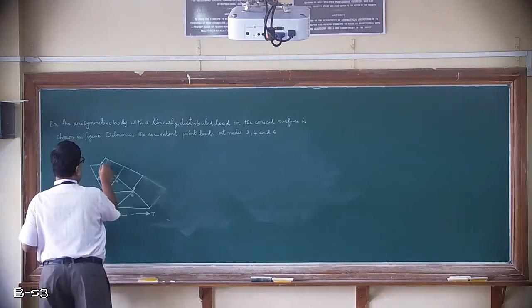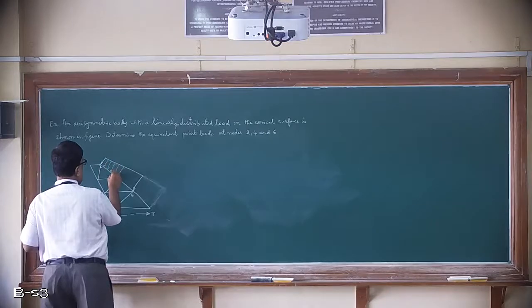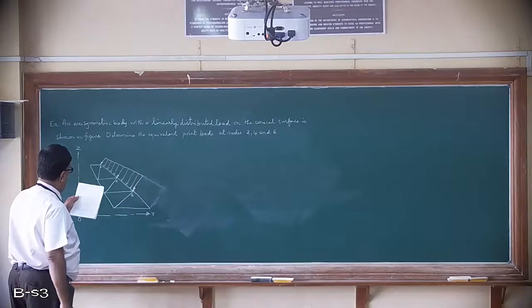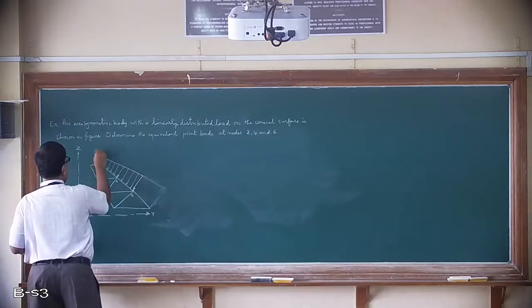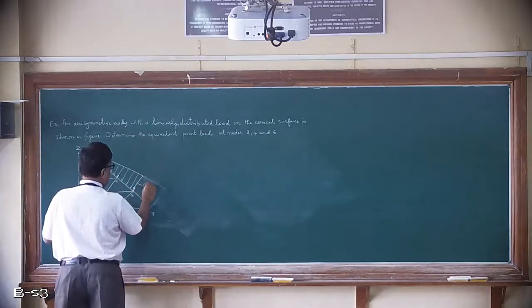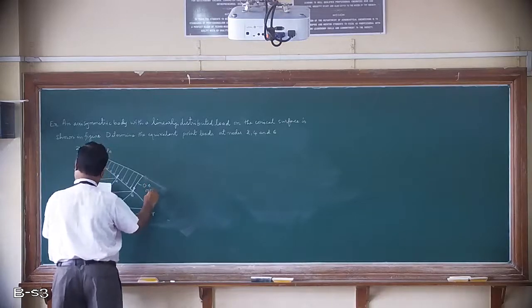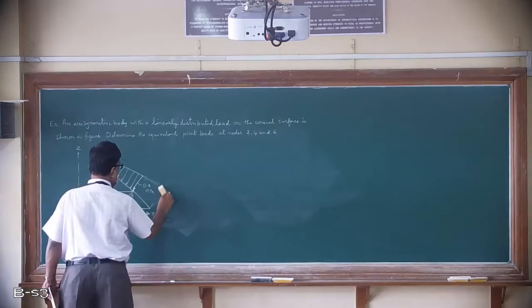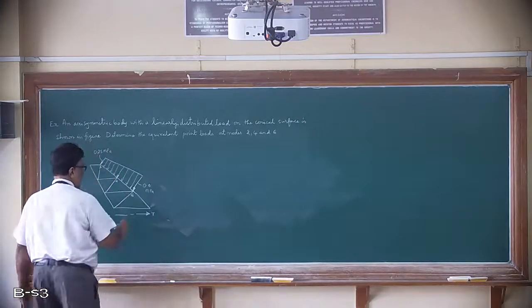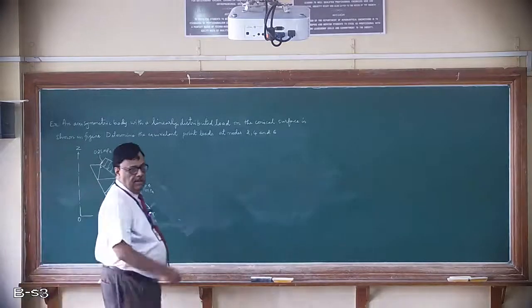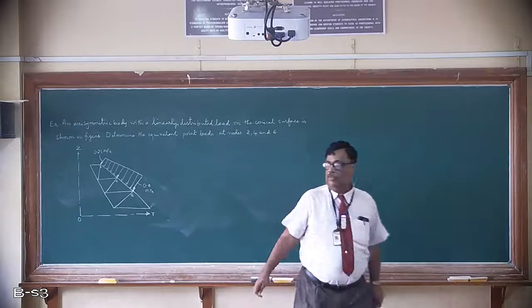Here, all these loads are acting now. These are, of course, acting in the downward direction also. And if you look at this, this is 0.25 megapascal, and here it is 0.4 megapascal. Okay. So we need to convert, because the expressions we have are only for the uniformly distributed traction, whereas it is varying linearly from one pressure to another pressure.